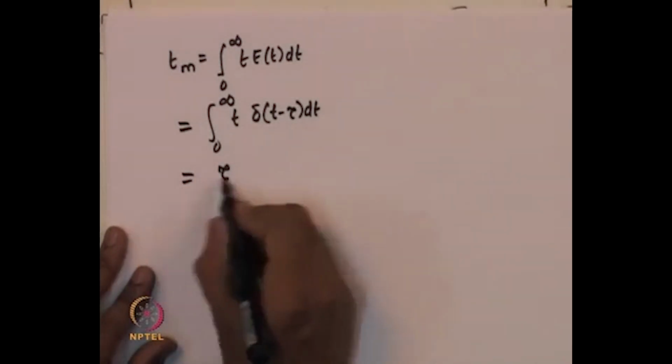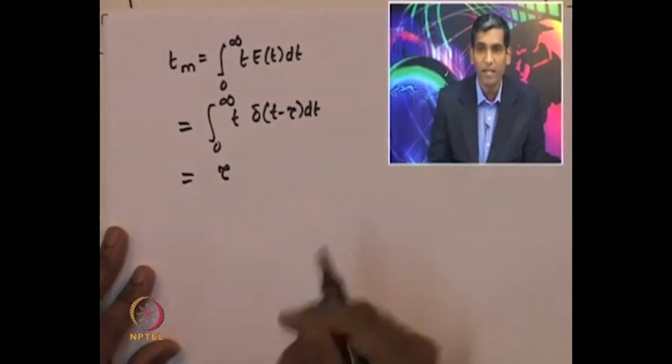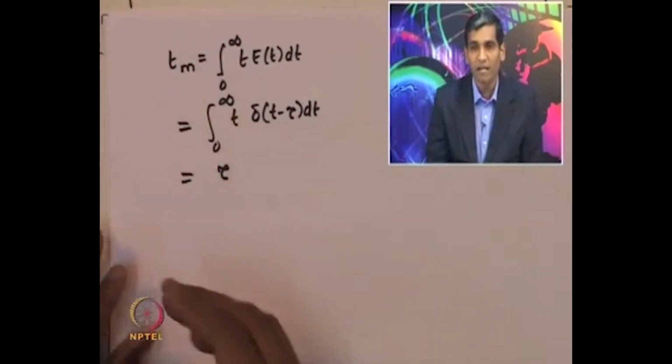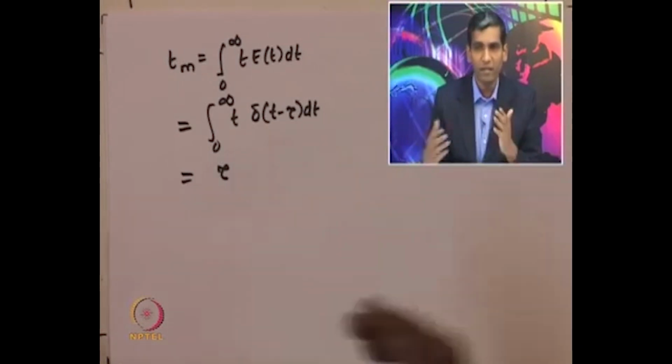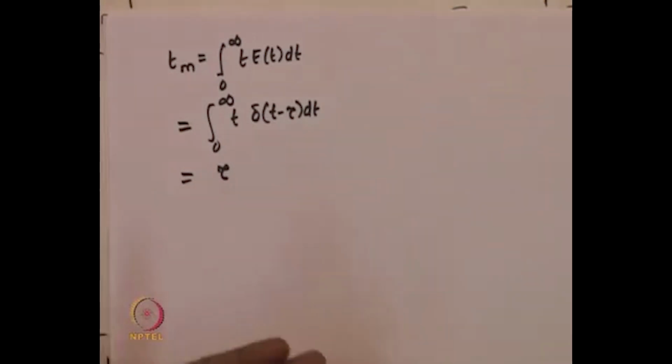So, the mean residence time is exactly equal to the space time, and one would easily guess this, because an important property of the plug flow reactor is that all material entering and leaving the reactor will have exactly the same residence time, and the E curve is centered at the space time. So, the mean residence time must be exactly equal to the space time of the plug flow reactor itself, which is also clearly shown by the RTD function.